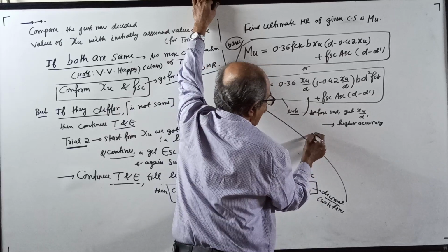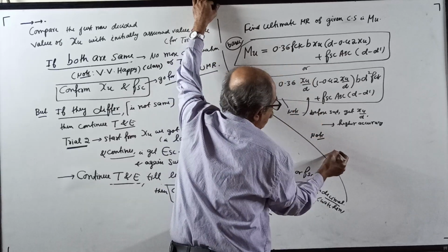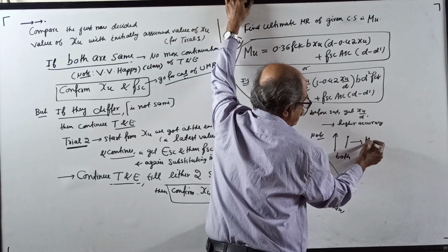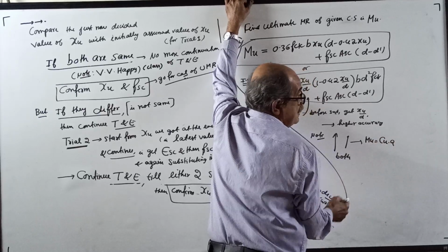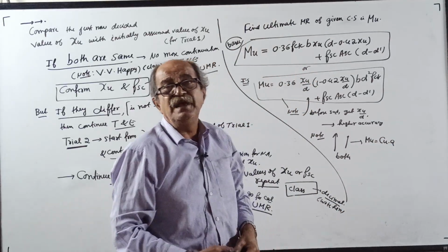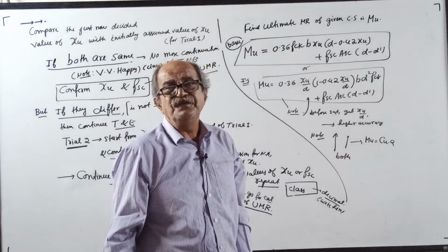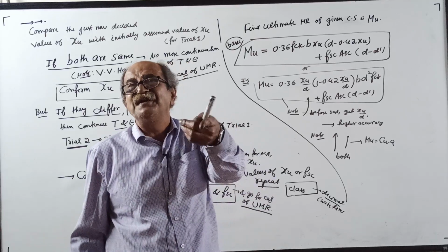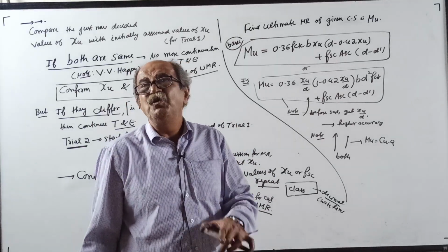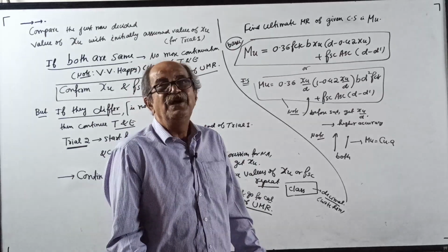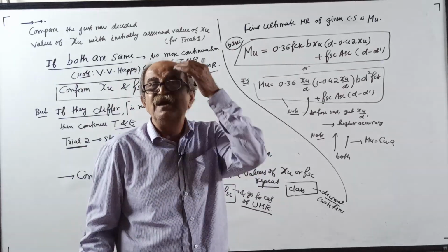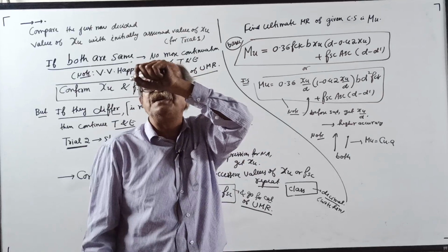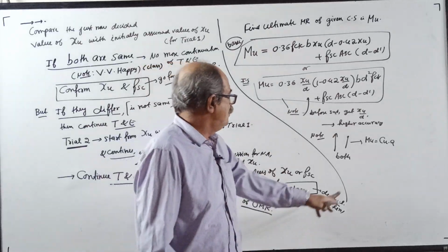Okay. Now, one last note. Both the above equations are based on MU equal to CU into A, or MU equal to TU into A. Here, like in the working stress method, it is usually not considered. Some people will tell it is not possible. It is possible. I proved it in the working stress method. If people challenge me, I will do it in limit state also and prove that it is possible. But it is too much calculation. You have to locate the line of action of forces, all the A, P1, Y1, P2, Y2, and the resultant. Leave it. So go for this one.